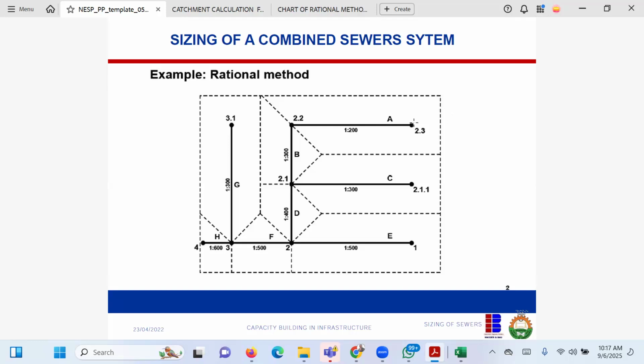So it means all the sewer will flow from here, some will flow from here, some will flow from here. Like I said, this is like the main. The tributary, the secondary pipe and the tertiary pipes are not shown. We don't need them. Like we said in stormwater, your job as an engineer is to design the main pipe very well. Once you design the main pipe very well, the connecting pipes, the tertiary pipes and the secondary pipes are no issue. But if you make a mistake in the primary pipe, your problem has started.